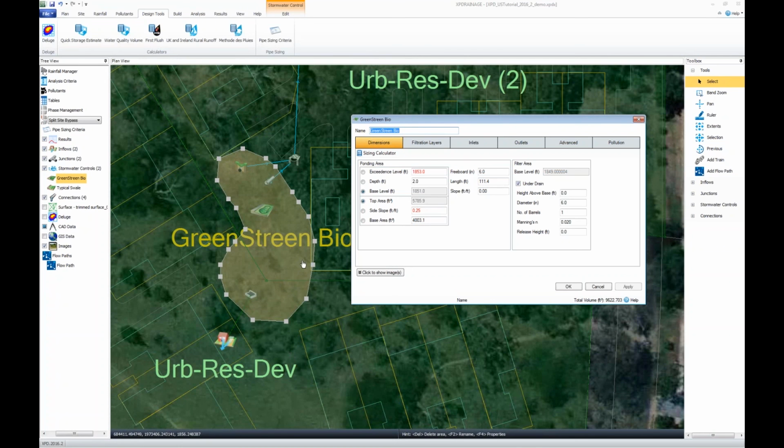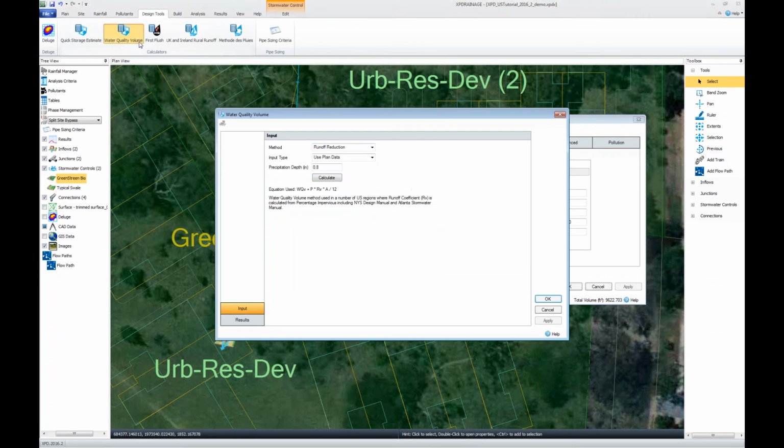I can save this all out to CAD. I can save a DWG with all of my layouts, all my plan, and someone could see where I'm proposing my ponds or my distributed drainage. So they'd know, I better not flip the egress of the site, that's going to be right on top of the pond. So that's really a fundamental item: the idea that we're referencing a surface, which automates our first pass of elevations, tying our calculations to the plan view. That's the real backbone of the software.